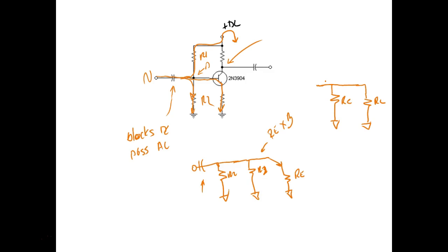Everybody okay? So what we're saying is that I wouldn't want an output impedance of 15 ohms driving an input impedance of 10,000 ohms. Right? You understand? Because I wouldn't get what? I wouldn't get maximum power transfer. So I wouldn't want a low impedance source to drive a high impedance load, or a high impedance source to drive a low impedance load. And that's why we're really trying to figure out this stuff.